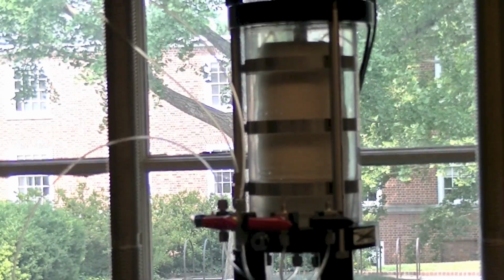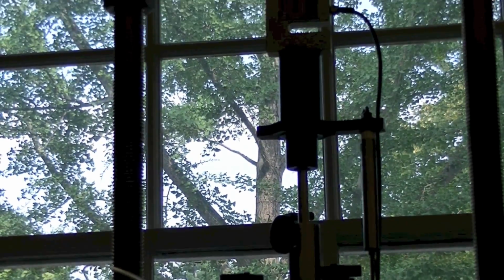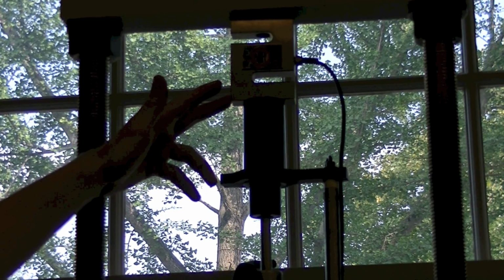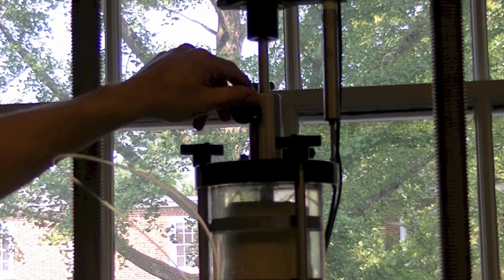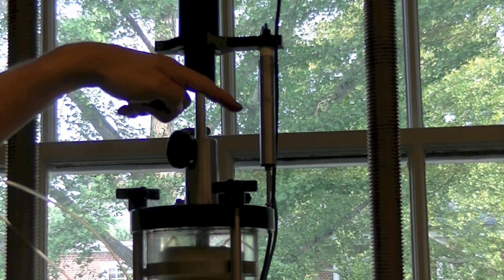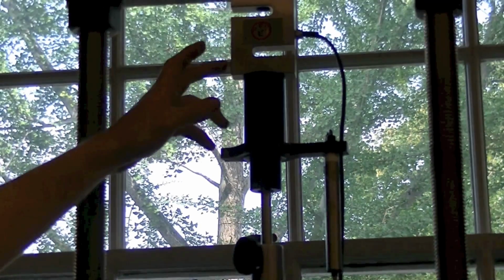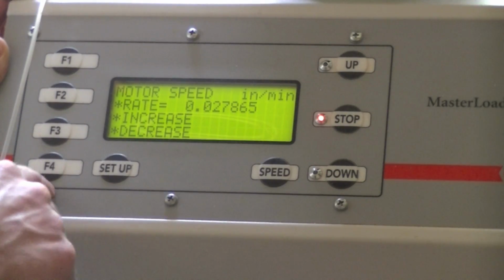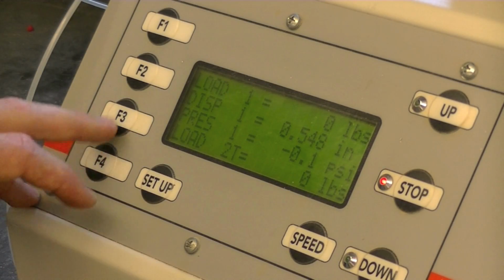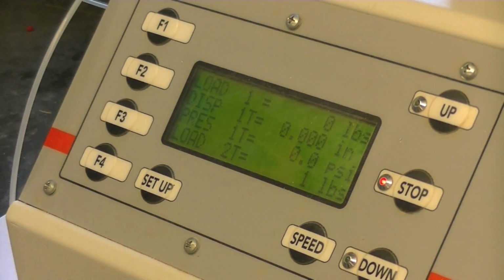Keeping the confining pressure on the specimen, move the triaxial permeameter to the load cell. Attach the bushing to the load transducer so the top platen is in series with the bushing. Position an LVDT so that it is capable of measuring upward movement by the master loader platen. Set the loading rate to 0.5% strain per minute. Tare the transducer and LVDT to 0.